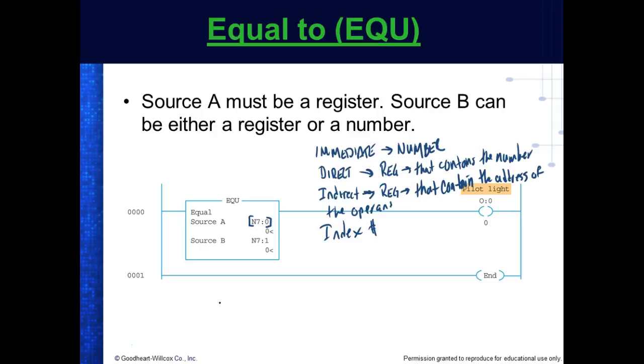Normally this whole time we come up here and I'll say output, then colon, then 1, and then a slash 0. If we put a slash, what are we addressing? Yeah, so this is the word, and if I put a slash, we're specifying the bit within a word. If I come over here and leave off the slash, I'm specifying a word, right? So I'd be working with 16 output ports at the same time.